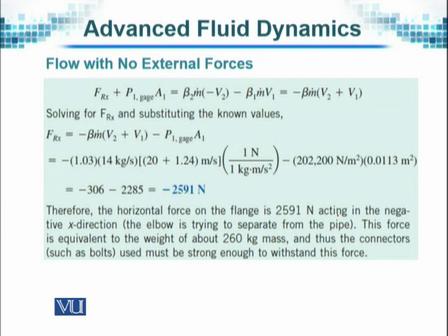And therefore, this will be F_Rx, that is the component of F_R in the x direction, plus the gauge pressure at point 1 times the cross-sectional area of the pipe, or of the elbow in this case, at that point, and this equals beta 2, the momentum flux correction factor that we defined in our earlier discussion, and that is required when we are considering momentum flux.